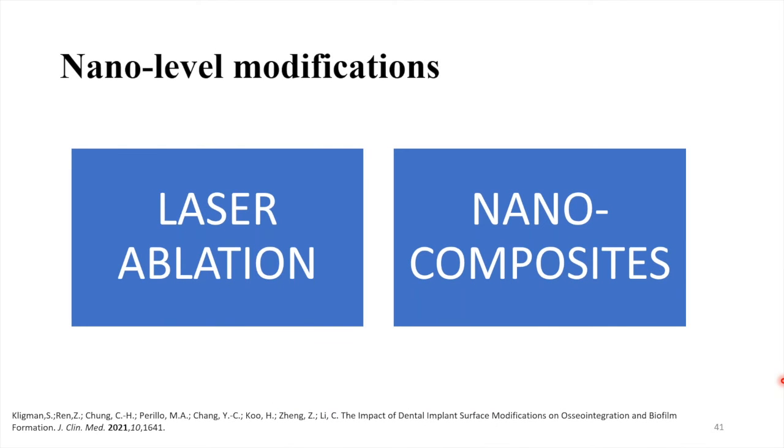At the nano level, modification increases the implant surface roughness and wettability, as well as the free surface energy, to enhance cell growth. Here the changes range from 1 to 100 nanometer, and it includes laser ablation and nanocomposites.